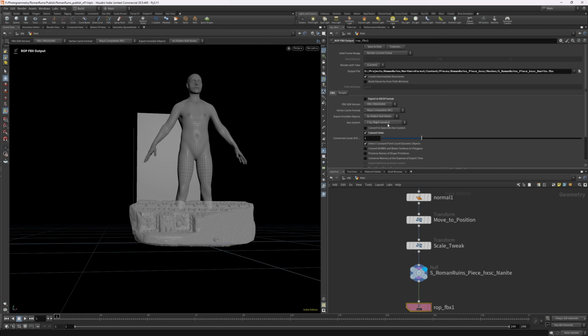There are a few things to think about here when you use the FBX exporter. First of all, this one comes in by default export in ASCII format, but you shouldn't do that. Every other program takes binary just as well, and Blender does not read ASCII format actually, so it's better to just not click it in, just not use it.